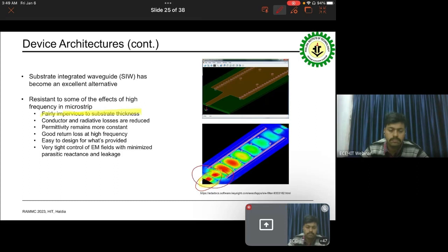If you look on the edges of this is where most of your leakage is coming from, is right around that microstrip and that taper. For the most part, you don't see a substantial amount on these vias. And I'm not sure what frequency this operates at, but it's not too terrible at lower frequency.